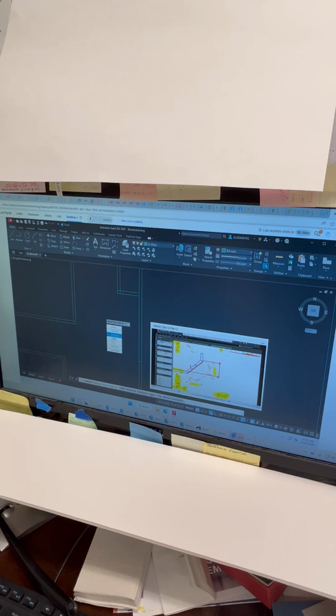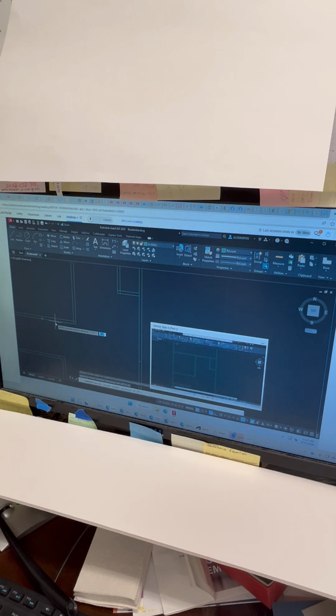So we're simply just going to offset it 3.5 inches. All right. So here's what I want you to do. Start the chamfer command. Here it is, right up here in the little drop down beneath fillet.